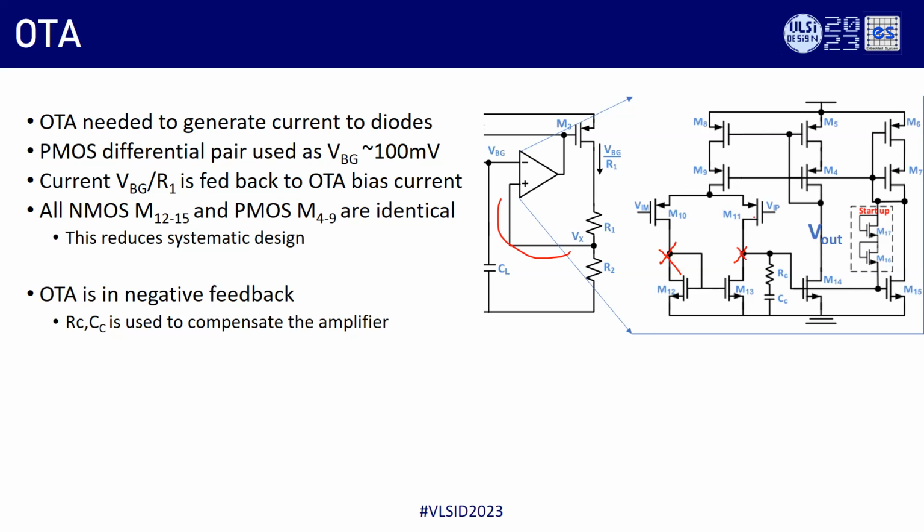Traditionally, first of all, this is the PMOS OTA, and this is the lag compensation, for which I have a couple of slides, as there are a lot of pitfalls and misunderstanding about how this RC works. I'll take this at the end of the tutorial. Basically we take this current and dump it in the back, so that all VGS and VDS will track. And this is the startup circuit.